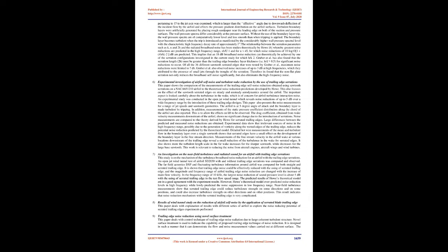Both experiments and theories reveal that the radiated sound power varies with the characteristic flow velocity to the power of five, which is thus more efficient than that when the airfoil is absent at low Mach numbers. Howe proposed a theoretical model to predict the sound generated by the serrated trailing edge of both the sinusoidal and sawtooth profiles.